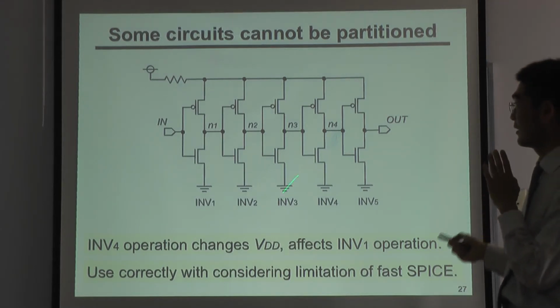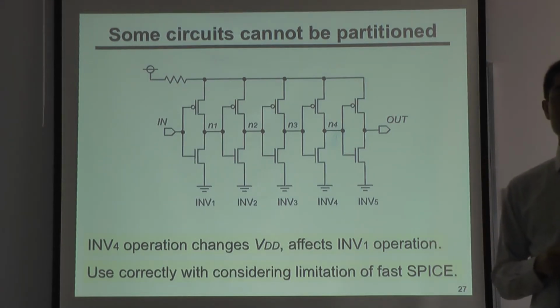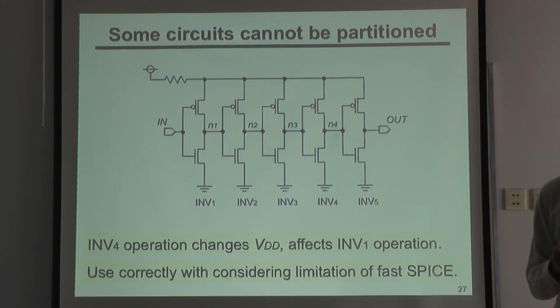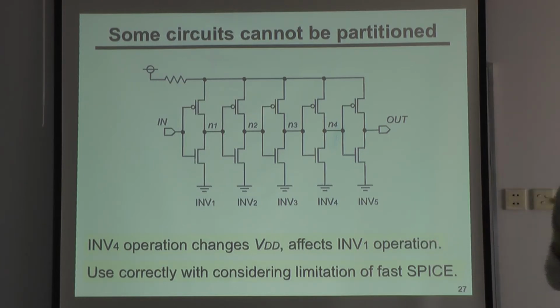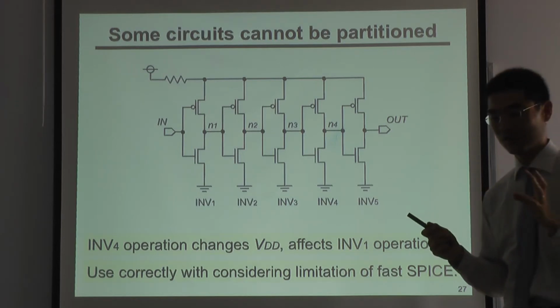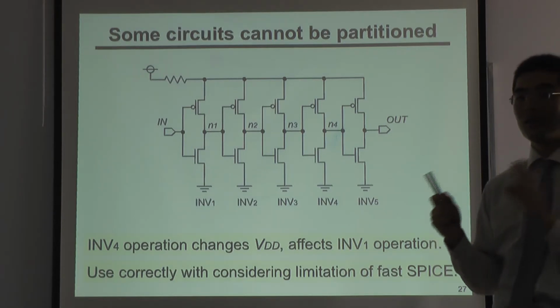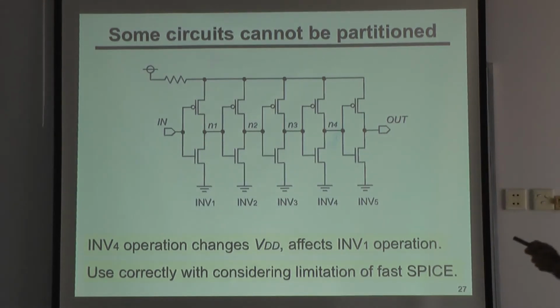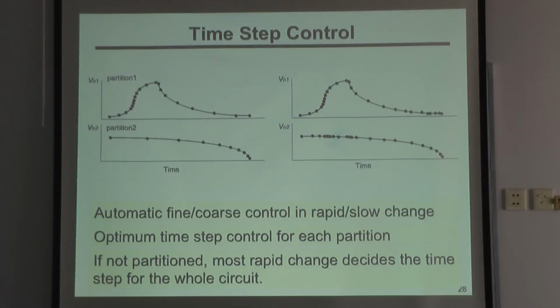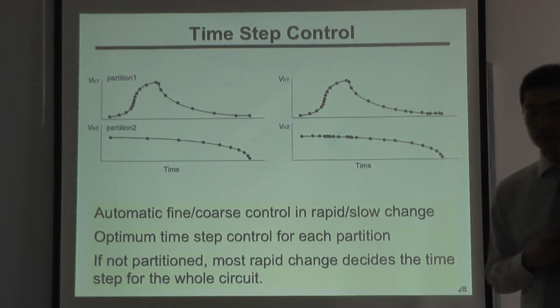So in this circuit simulation, Spectre gives us more accurate and fast results. And UltraSim takes more time, and it also degrades the accuracy. So we have to pay much attention to whether we should use UltraSim or not. And also the fast spice.